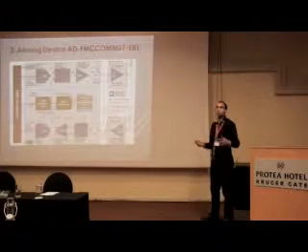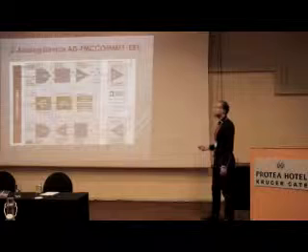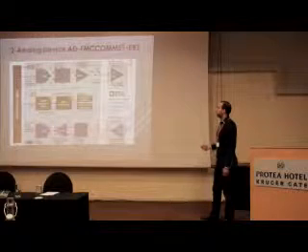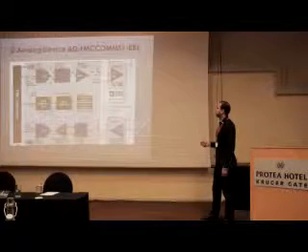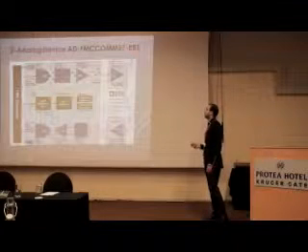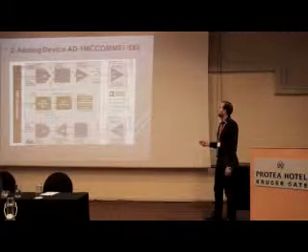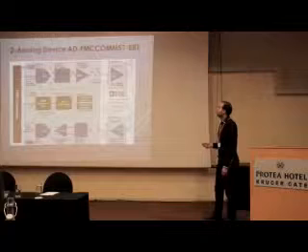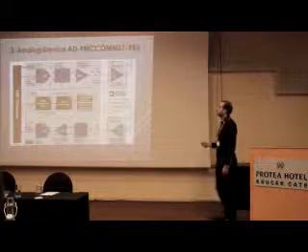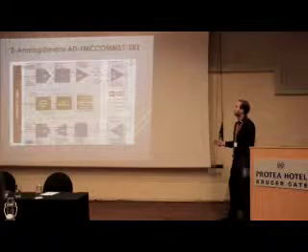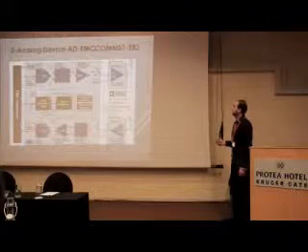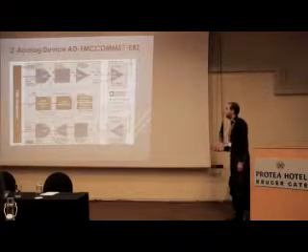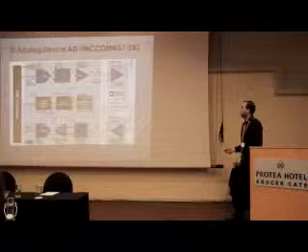The second component is the radio board. So we have three stages. The first one is about the clock, how I generate the clock. So the clock generator is just there. Then we have the clock distribution for all stages, and then we have synchronization. The first one is the transmission channel. So there is a digital to analog converter. This is a 16-bit DAC. Then we have an IQ modulator, I will explain that just after. So working at this frequency. Then we have the gain, so 20 dB fixed gain. So this is the transmission channel, and then we have the reception channel, which includes demodulator, VGA, and ADC.